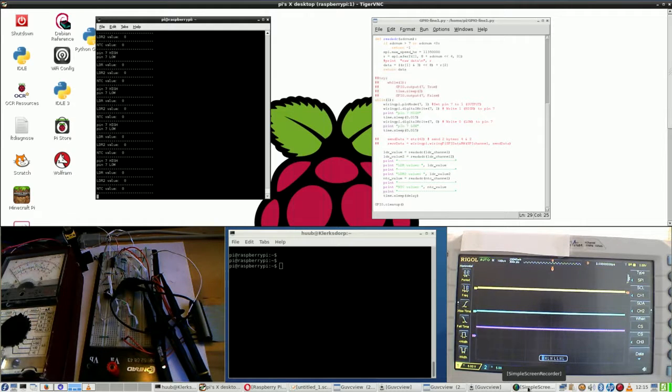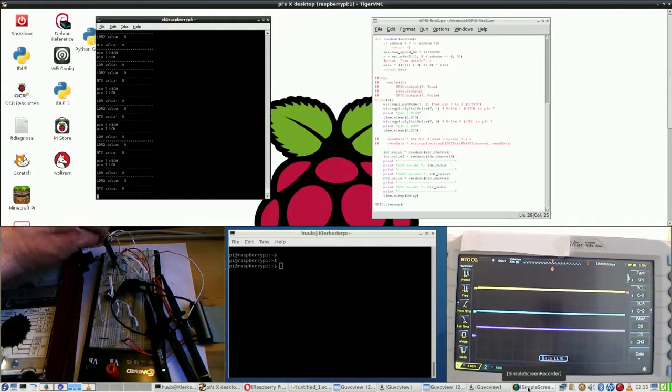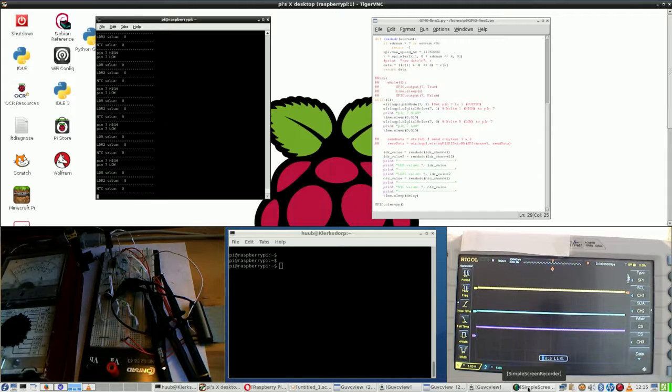Last part for this episode. I have put the multimeter on setting of 1.2 volts, and this means that I will measure from, let's say, this point, which is connected to earth, to ground, and then I will measure several other points to begin with here, and here it gives a very low value even on the 1.2 setting.